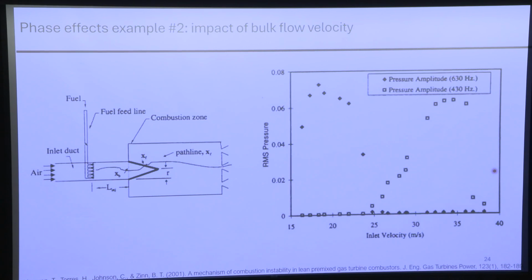And so at the beginning, you can see this frequency lines up and then goes away, but then this frequency pops up later and then goes away. And so we see this periodic appearance and disappearance, and as we go through, we'll talk more about why inlet velocity matters and why the different frequencies are popping up. But I just wanted to show some actual data where you see exactly that shape that you'd predict by multiplying sine waves in the Rayleigh integral, in actual data from turbulent flames.